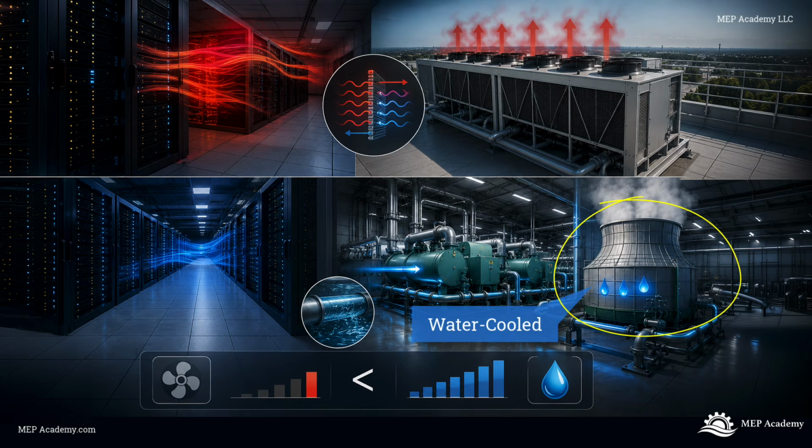Water-cooled systems are often more energy efficient because water transfers heat more effectively than air. This becomes especially important in large data centers with massive cooling loads. Water-cooled systems also work well for high-density environments because water can move large amounts of heat more efficiently than air alone. That is one reason many large hyperscale data centers use water-cooled central plants. Another major advantage is economizer operation. During cooler weather, cooling towers or fluid coolers may help reduce or partially replace mechanical refrigeration, improving overall efficiency.